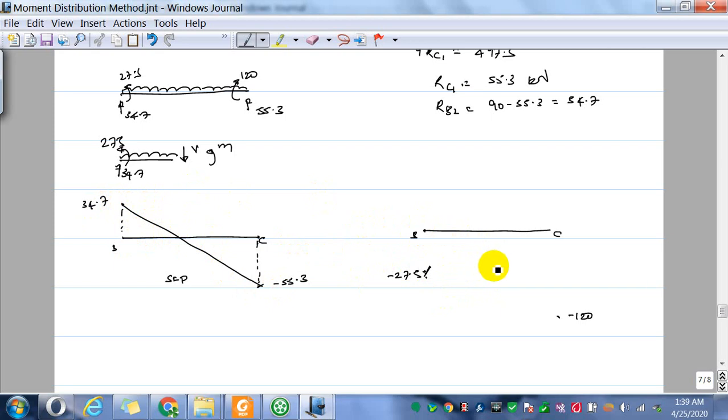The slope of the bending moment is positive, it gradually goes to 0, then it's increasing in the negative direction. Now we can check whether this bending moment diagram is going to be a shape like that, or a shape like that. There are two options. The best way is to see whether this bending moment diagram will have a 0.